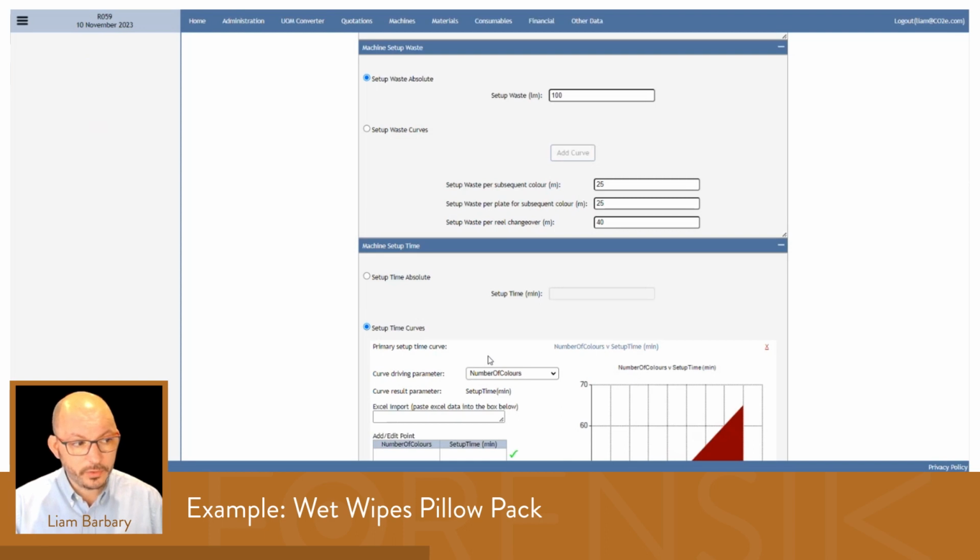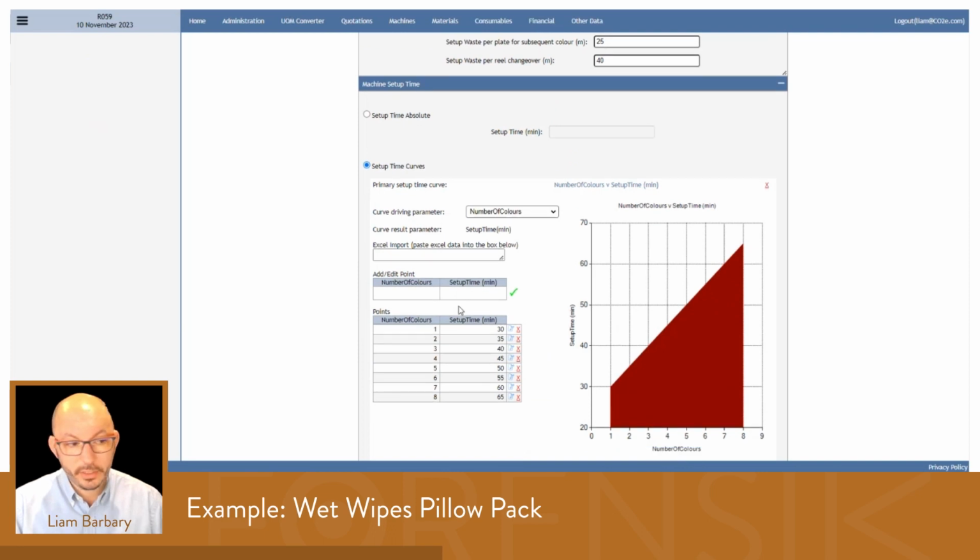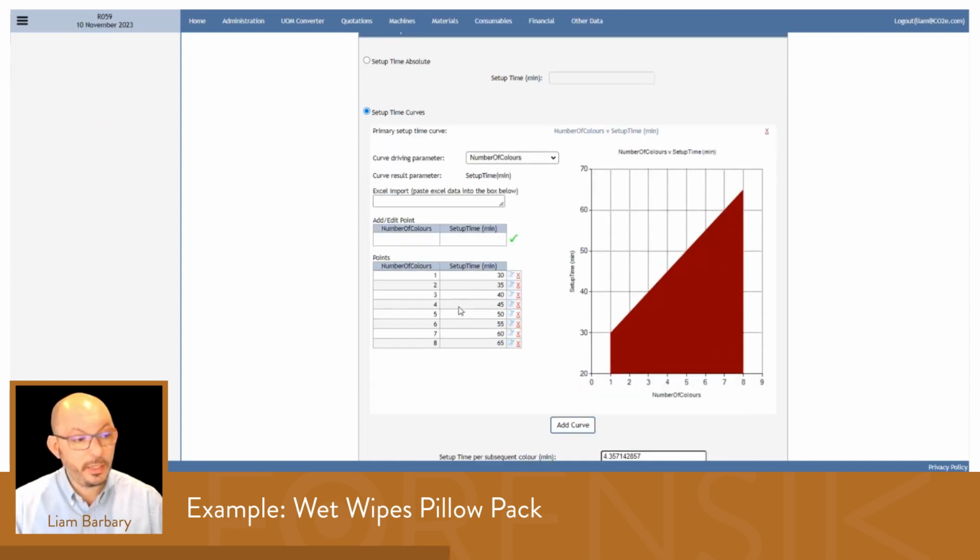And again, those considerations for setup waste, for the wasted raw materials, and the time for the wasted time during setup, for ink matching, color matching, and plate registration, those things need to be considered, because all of those will drive extra time, which is extra CO2e, and extra waste, which naturally, the more product we waste during our production process, the more CO2e we're going to have.